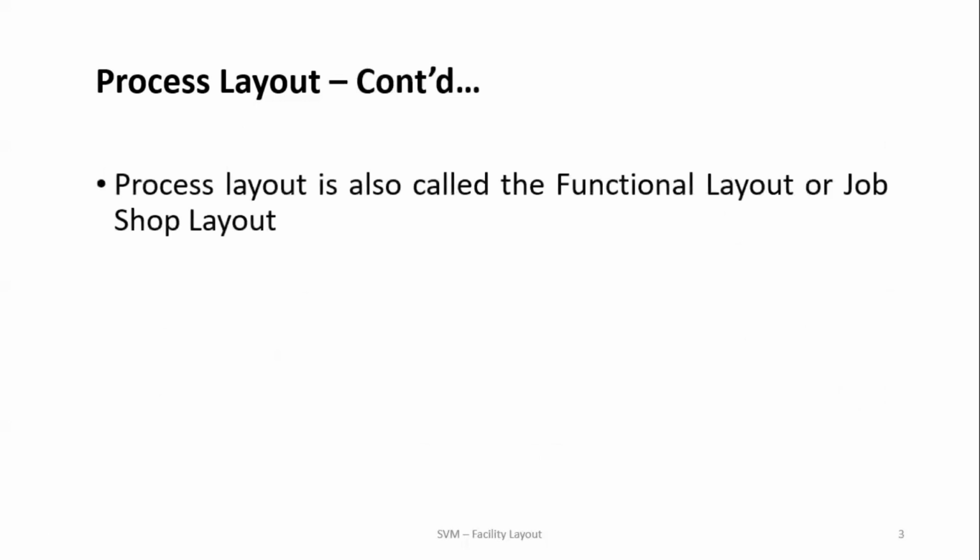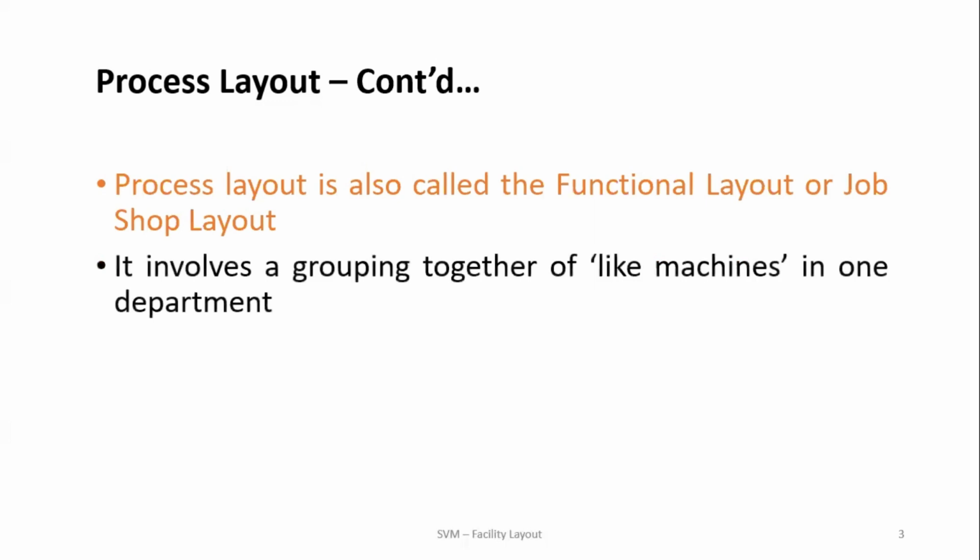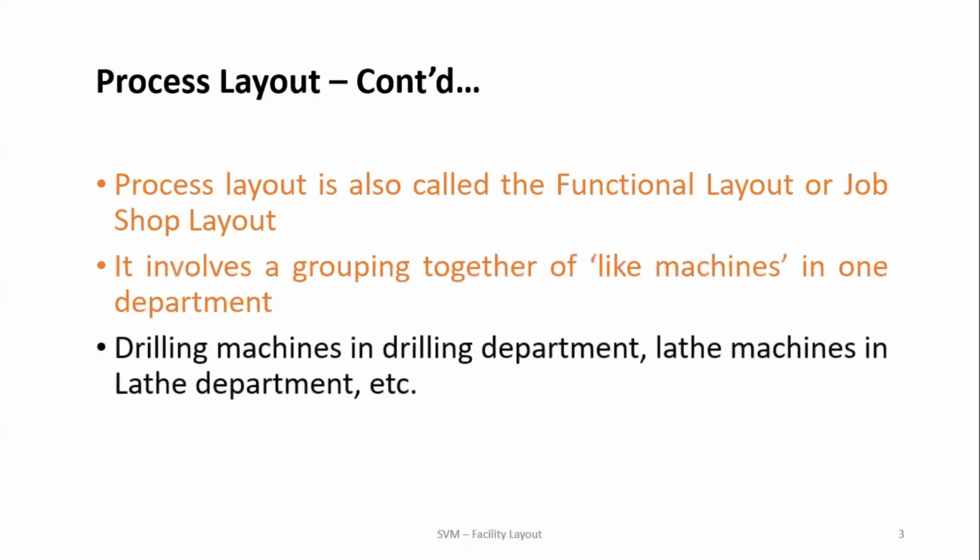It is also called a functional layout or a job shop layout because all machines are organized based on the functions. It involves grouping together like machines, meaning similar machines, in one department. Drilling machines in the drilling department, lathe machines in the lathe department, etc.